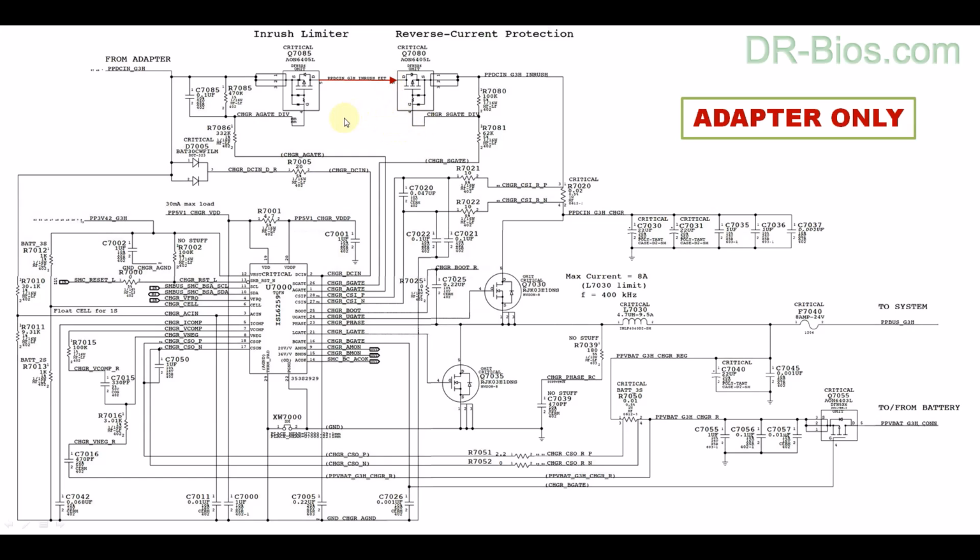The IC that received a command from SMC on the previous step to connect voltage, it gets its SGATE pin low, and it drives this MOSFET, and voltage passes through drain pin of this MOSFET to its source pin, and after passing a resistor that you can see on this slide, it arrives at the back of high MOSFET.